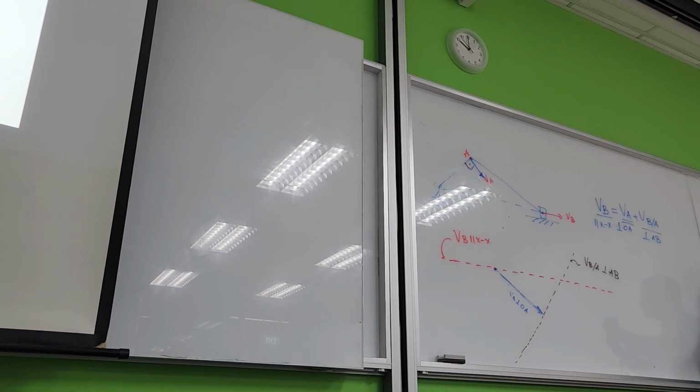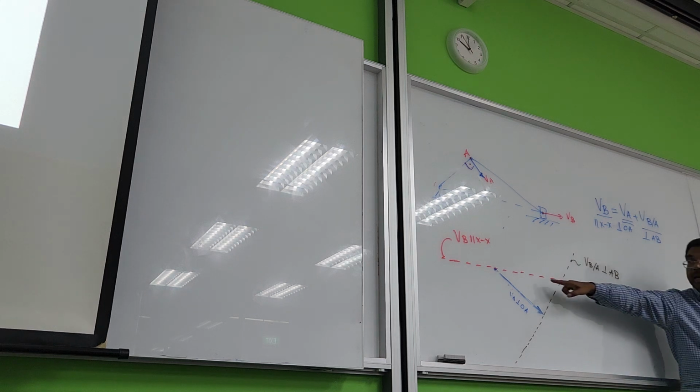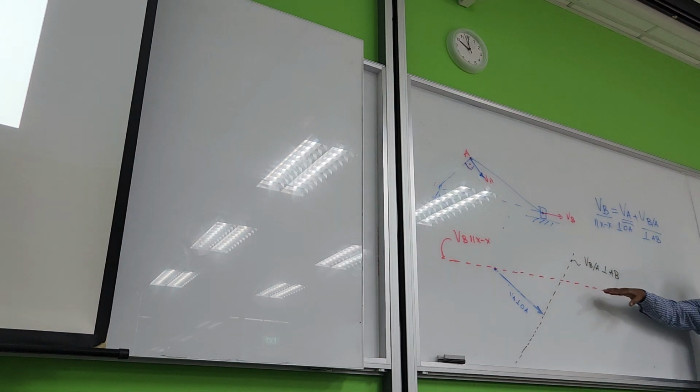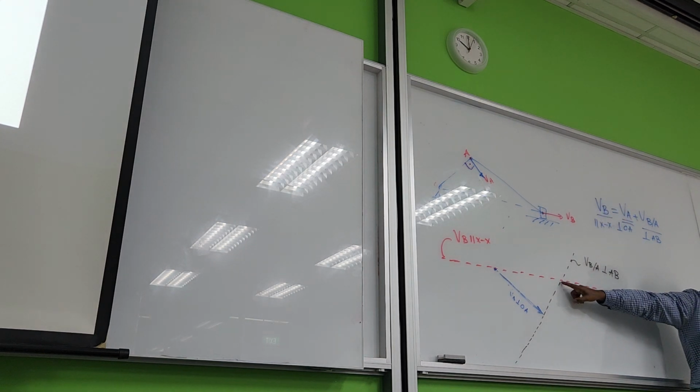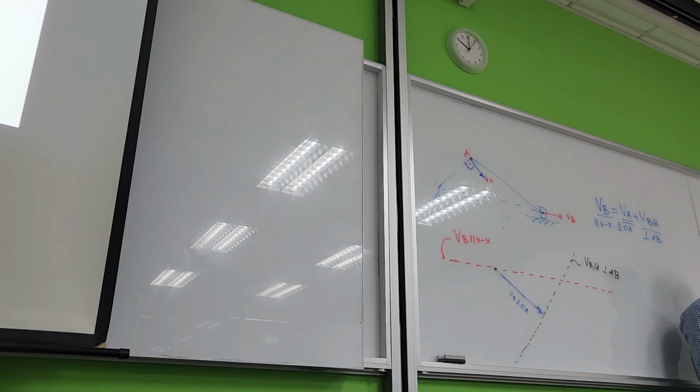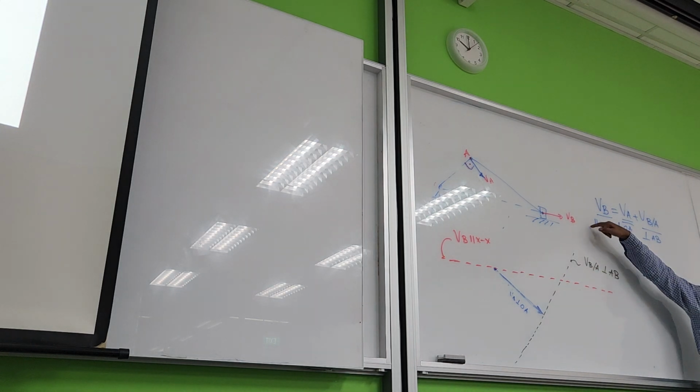So to close these things, our red line, which is BB, should come to the right, and our BBA should come upward. Then they can intersect there and close the vector polygon. There is no other way, because our equation says they have to close. Can you see that?